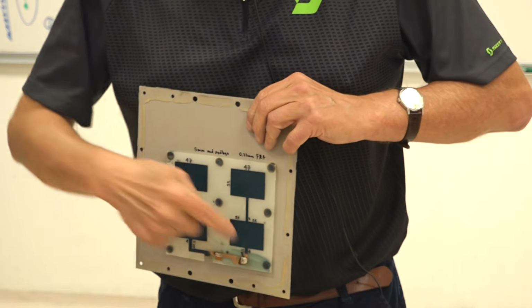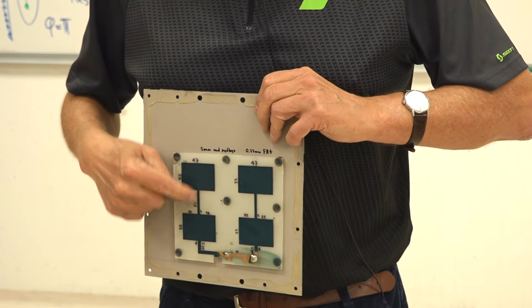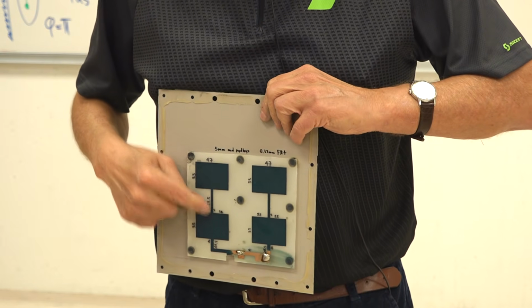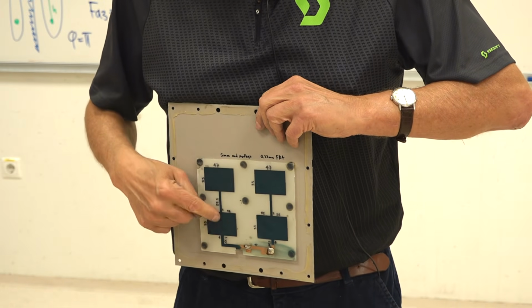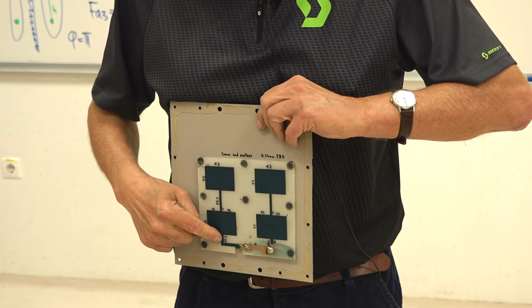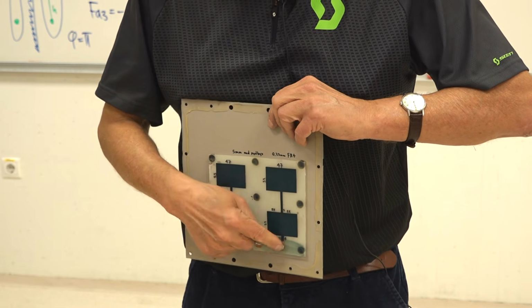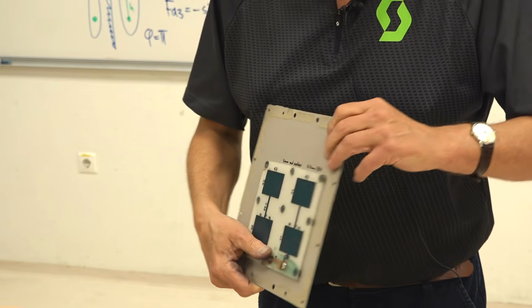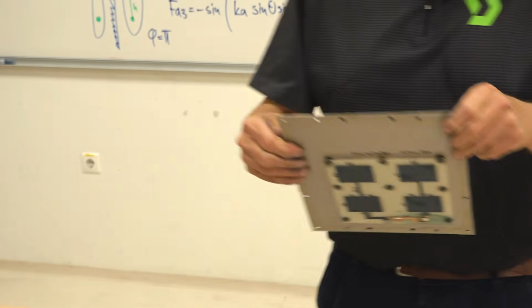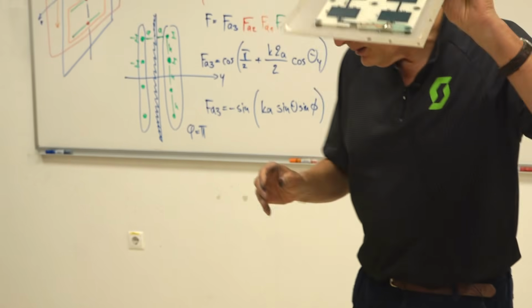It has 4 patches. Each patch has around 200 ohm impedance. This is lambda half, 200 ohms plus lambda half. It's connected to this patch. So 2 patches at 200 ohm, you come to 100 ohm here, 100 ohm here, and these 2 connected together, they bring you the 50 ohm to the connector. So impedance matching is also installed here. This was working pretty good, made in India.